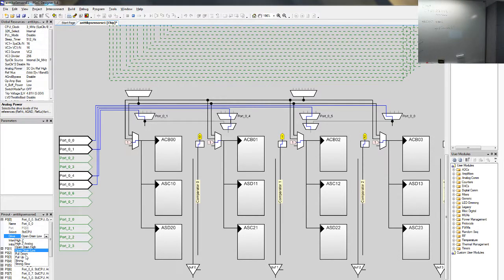For example, where you can use these is as an input. Okay. If you have a push button on your circuit, a high side push button at plus 5 volts, and you want to use that to connect to some circuit, you need a resistor here to pull it down.